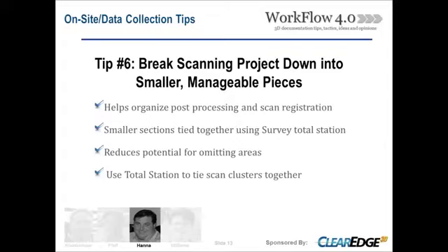So as both Mike and Larry have pointed out, it's absolutely essential that we use survey total stations with all our scanning projects to aid us in the post-registration process, as well as it really enables us to break a building down, for instance, into smaller chunks that are much more manageable. We found that it reduces potential for omitting areas, and also helps us in the scan registration where we can tie all those clusters together, floor to floor, for instance, and have high confidence that we've got good spatial data there that's as accurate as we can make it. So that's how we attack a large project.